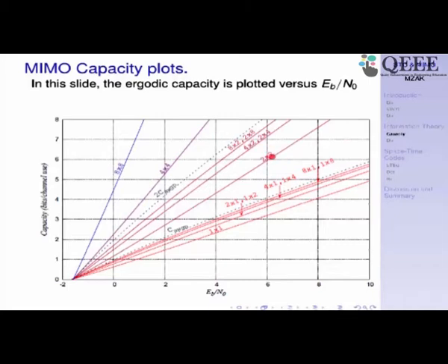Similarly, even with 2 cross 2 antennas, if you keep the number of transmit antennas fixed and increase the number of receive antennas, it is going to converge to the capacity of two SISO channels in parallel. That is how it is going. But if you increase both the number of antennas, 4 cross 4, 8 cross 8, the gain is massive. So that is the prime benefit of MIMO. You are able to increase the capacity linearly with the minimum of the number of NT, NR antennas. That is what is called the benefit or the gain of MIMO.